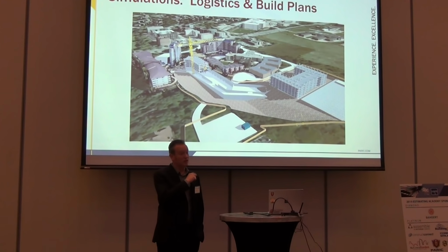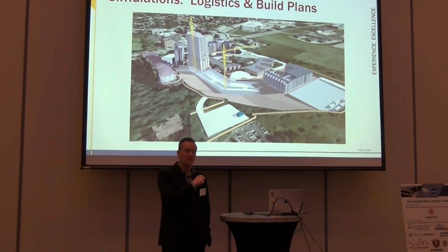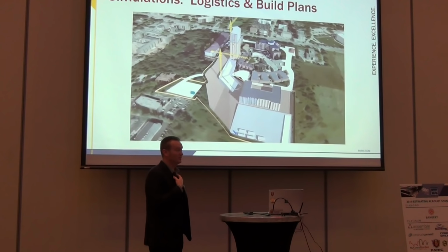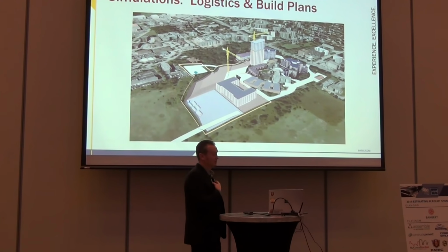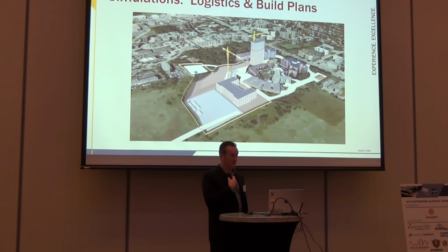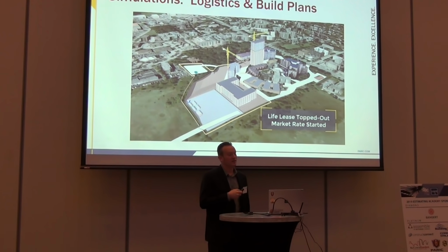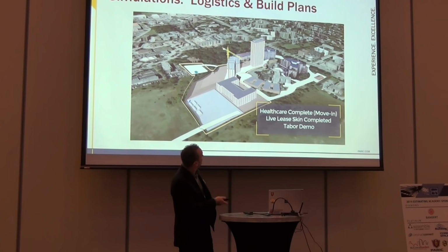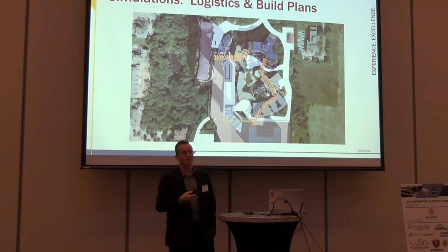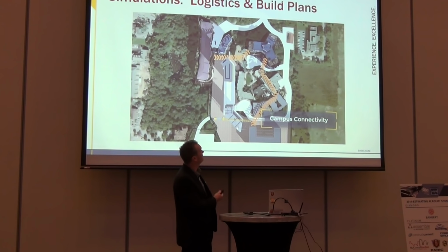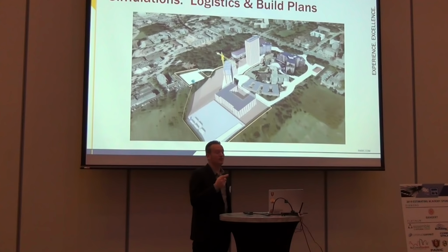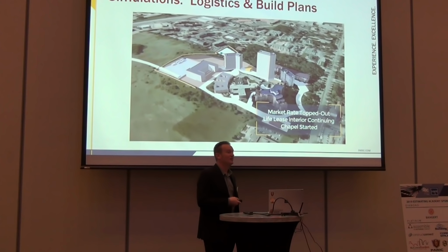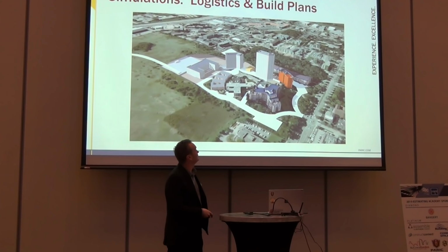In fact, this ultimately changed significantly from this image because when they saw this, they saw things they didn't realize before, right? So if I'm an estimator and I have to do a conceptual estimate, I want to get a conceptual estimate that's close but quick. How can we get there as quickly as possible? This allowed us to quantify the topography on this job site. Looking at it, it doesn't seem like there's a lot going on there, but it drops 90 feet from one end of the site to the other. It's about 50 acres, right? It's in a northern state where they get frost and freezes the ground, which is good and bad. Depends on what we're building at the time.